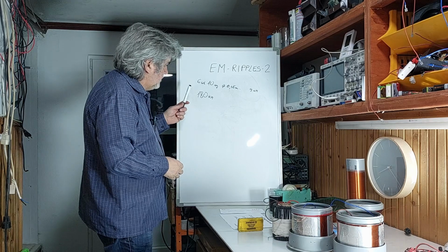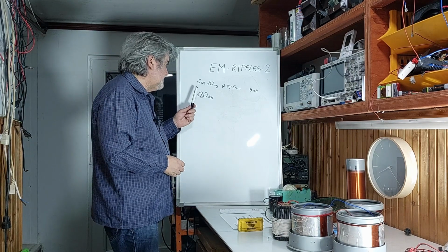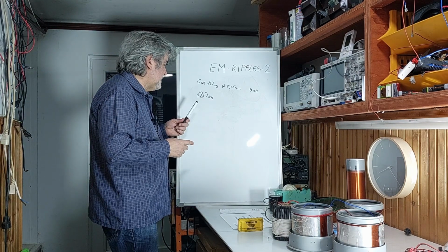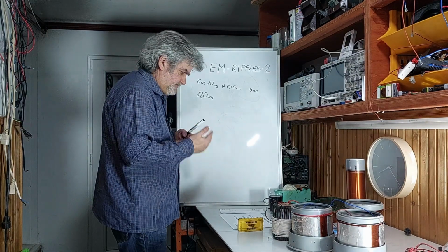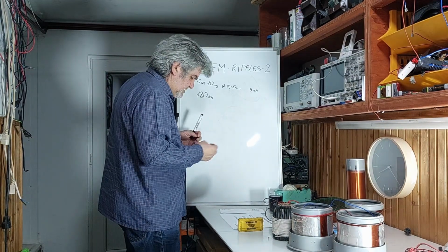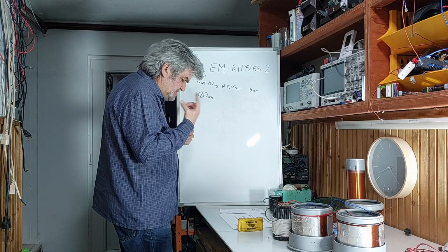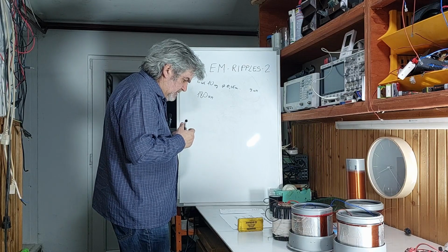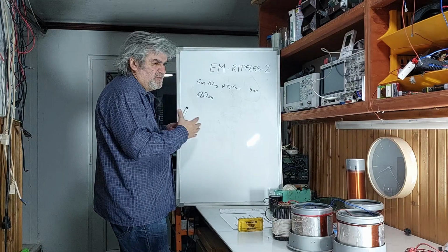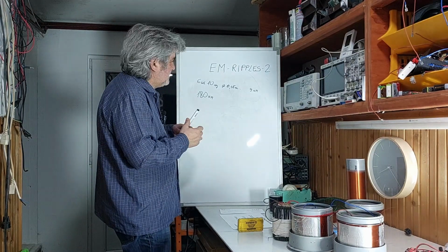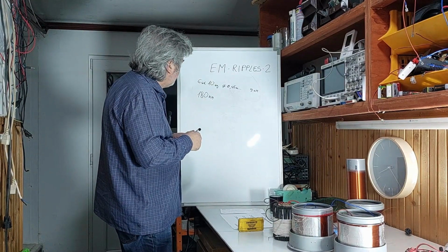When I made the calculation, I drove all 6 coils in series with 2 kilohertz, which is like Hastings suggested. There was no current. Why? Because there is so much capacitance between turns. So I gave up on that.